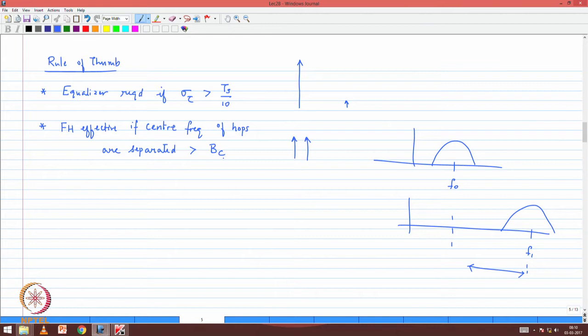And of course, why are we saying anything about the coherence time? Yes, you must be doing channel estimation. Channel estimation is needed whenever you exceed coherence time, when the duration of demodulation becomes larger than coherence time, because that's when you know that the channel has changed and therefore you must be adapting your channel estimates.